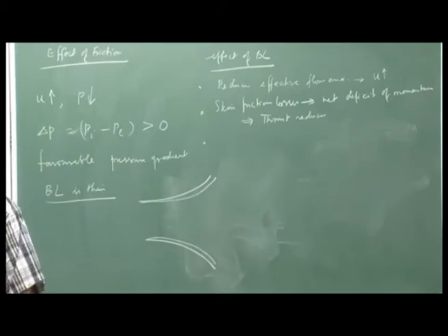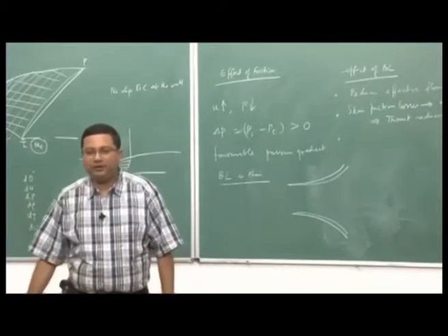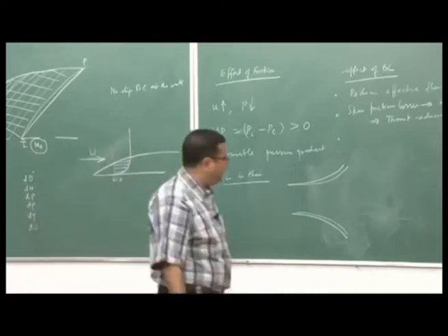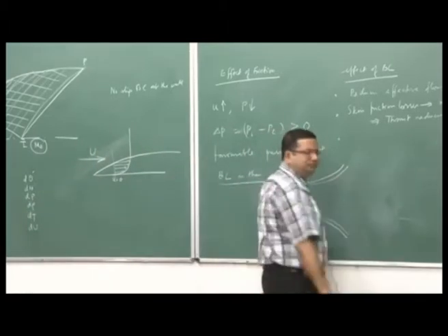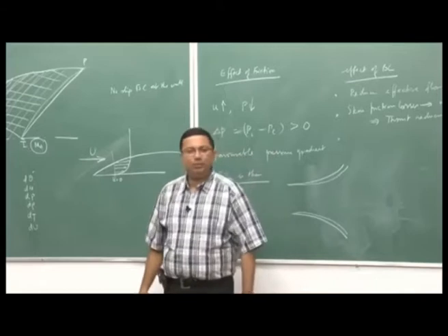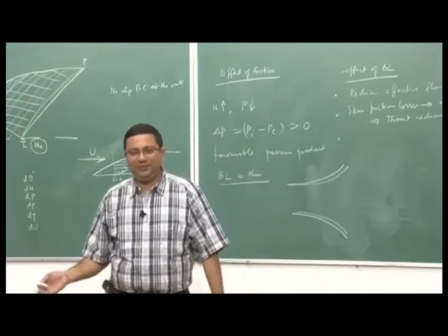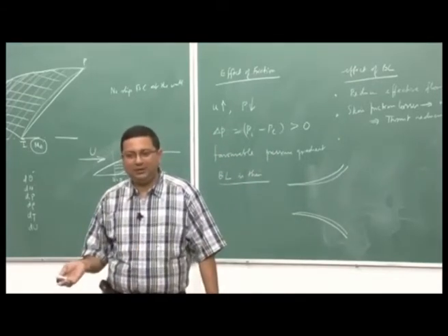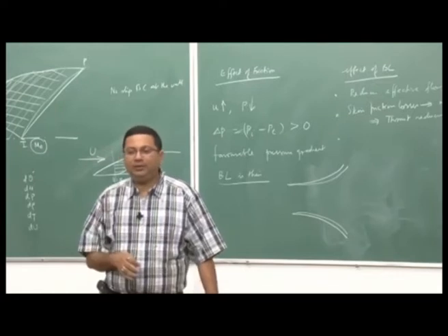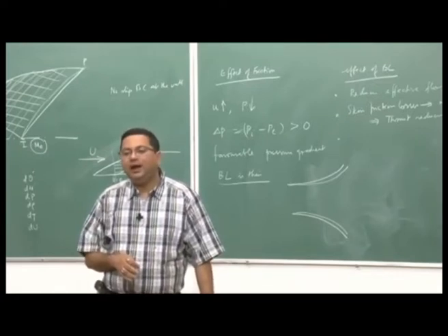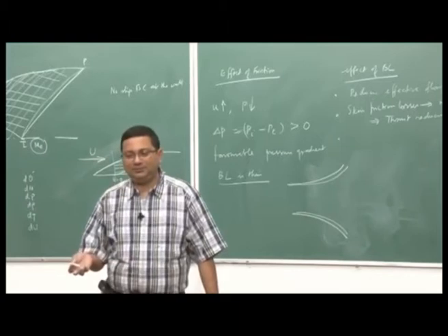Because of this boundary layer, the flow is no longer isentropic. Let us assume that we had designed an ideal nozzle, right, but now it is no longer ideal, or conditions have changed. So, it may so happen that we get an overexpanded nozzle.